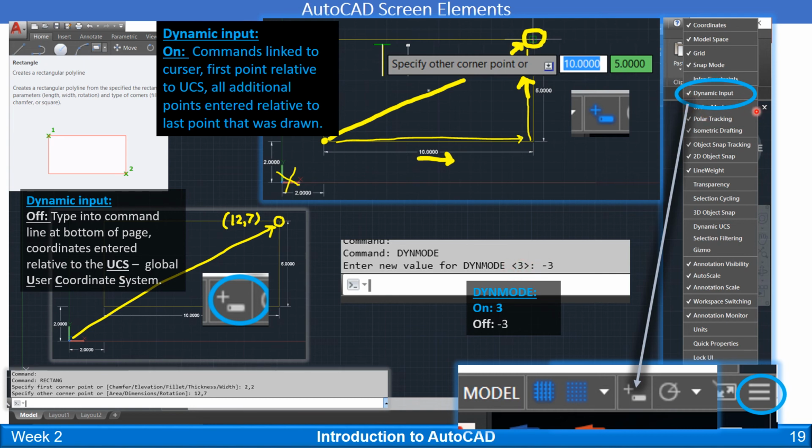If your dynamic input is on, if this little guy is blue, what's going to happen is you're going to get another command line that shows up right next to your cursor. It's going to follow your cursor around on your drawing area, and you're going to type commands in right next to your cursor. And the commands are a little bit different.